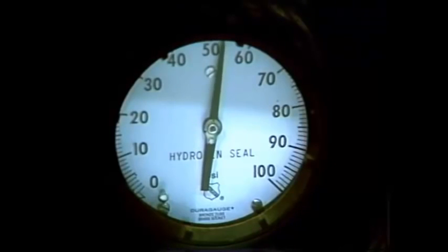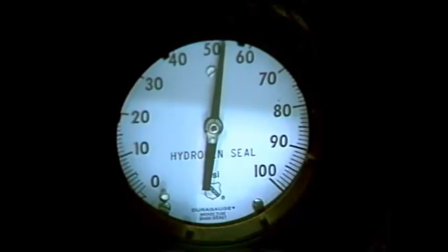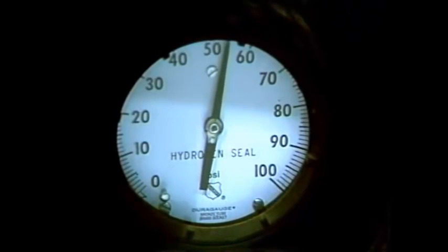This maneuver takes several hours to complete, so it is clearly necessary to get an early start and plan the complete operation when returning a unit to service. During a short shutdown, say overnight or even for a few days, it is normal to leave the generator rotating on the turning gear and to keep the generator charged with hydrogen. Of course, if the generator is air-cooled, then we would not be faced with hydrogen charging.